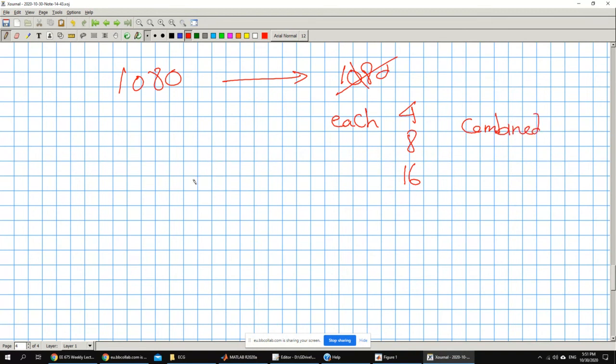If I'm looking only at the positive spectrum, this is as if I'm computing the energy in each one of these bands together. So this band has many points, this has many points, and I'm computing the energy within each band, so that a small variation within that band wouldn't really matter. This will also make the noise within each one of the values of the Fourier spectrum a little bit lower. So this can be very useful.